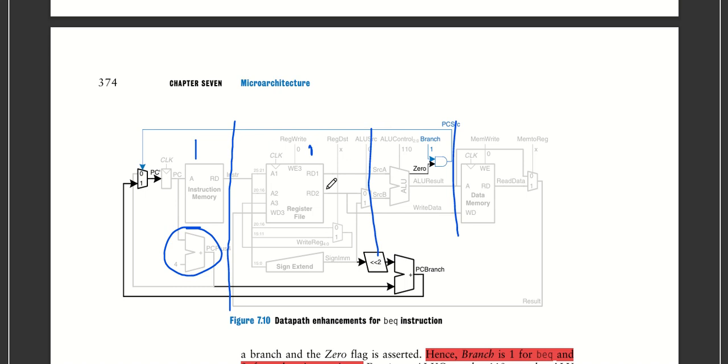The single cycle does everything in one big clock cycle. You give the control signals and you make everything rush until it gets to the output. You give the control signal and you know the time the electricity will take to travel from this point to this point. That's the time you know, so you use that as your clock cycle.